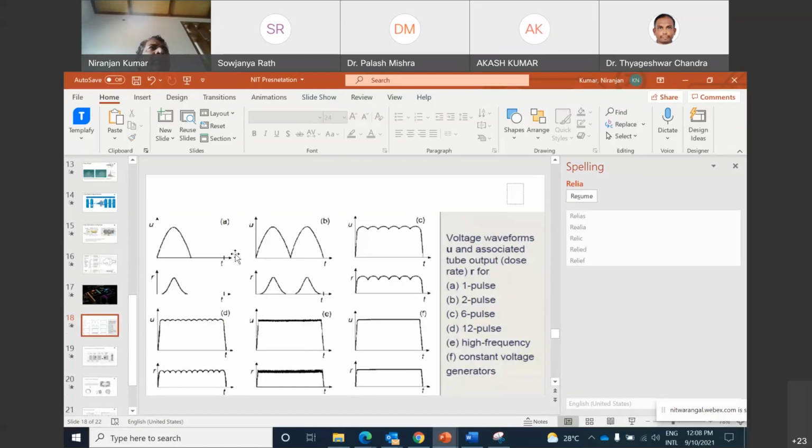Unfortunately, I cannot present it because those are company secrets. But we have developed, you can search the Pierce gun theory on Google, a technology where we can modulate the kV in less than 10 seconds. Not through discharge, but through resonance. If I trigger the resonance, I can take all the energy and store it somewhere, and whenever the next pulse is needed, I can force the energy again. So it's like a 10 nanosecond rise time and 10 nanosecond fall time.